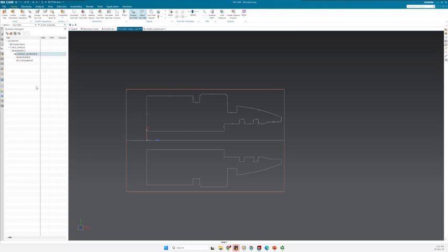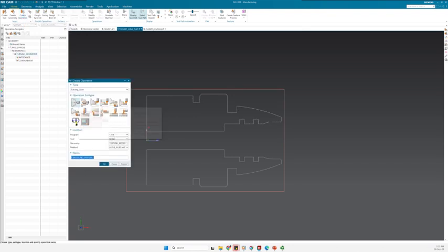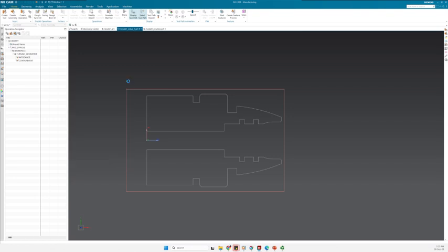And then in the next video, I can show you how to define the main program. Other than that, I can also describe a little bit here. You can see already defining the tool, defining the geometry, and defining the operations. And you can see all types of operations here. So for example, if we are defining operations, we are first defining what type of operation we are looking for. And then we need to define in which program, what is the tool, what is the geometry, and what are the methods. And then we can call it a process.